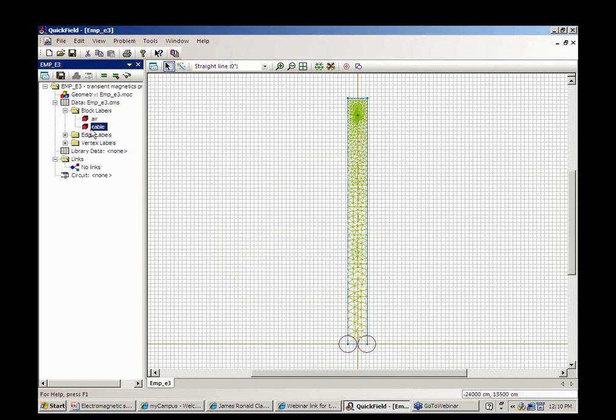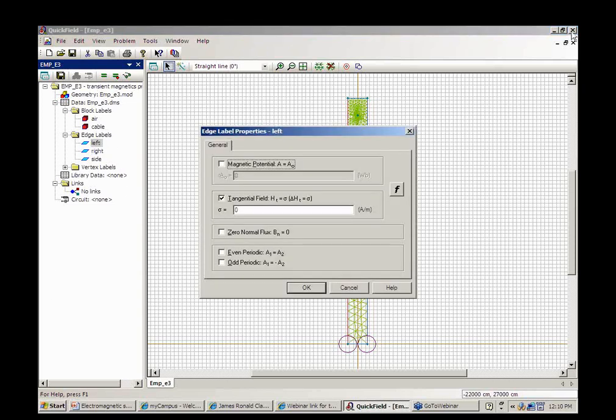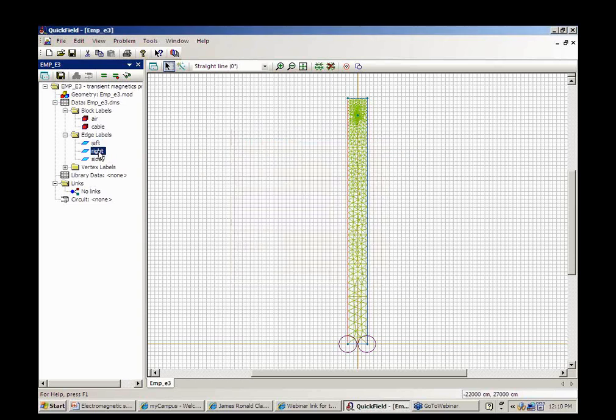Once again, I have a cable. The cable has a diameter of 1 centimeter and a length of 300 meters. So the slow component of the EMP is going to be more problematic for very long conductors because the Earth's magnetic field, roughly 50 microtesla, is changing, and it can result in very large currents being established in long conductors and power lines and so forth, and result in transformer failure and various things that aren't good. It's a vertically directed pulse.